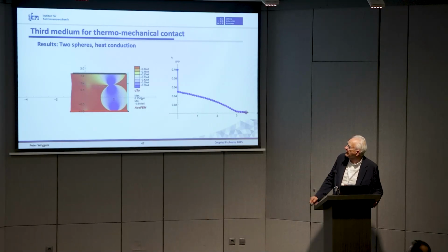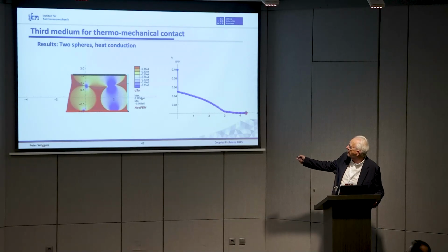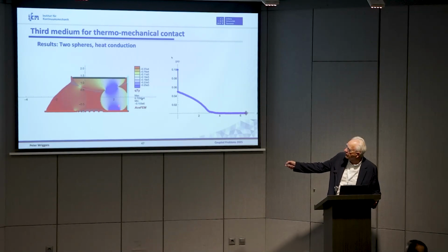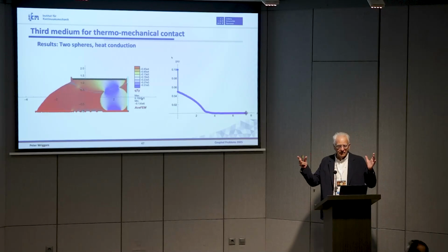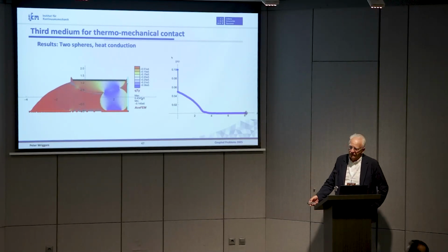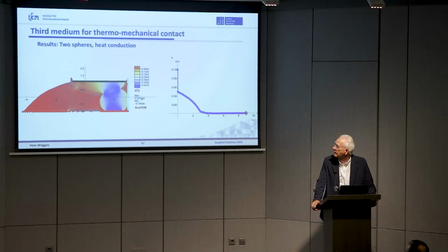And the heat transfer basically goes here. This is sort of the gap function. And then again, when it starts to move, you have a little bit of heat transfer there as well, but then it moves out and the heat transfer goes away and is basically only going through this. So it's a little bit complicated problem, but you can model this problem quite nicely with this third media approach without thinking about complicated contact mechanisms.